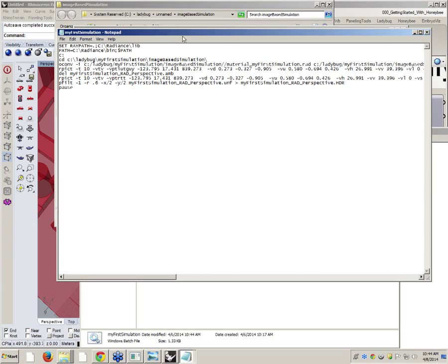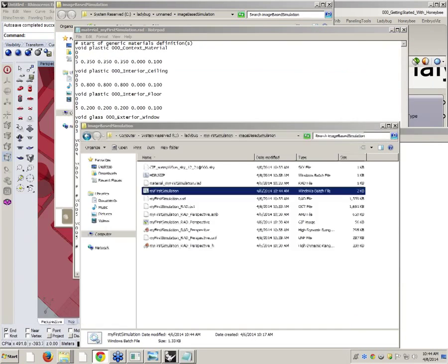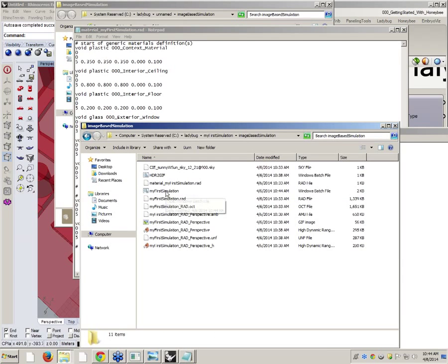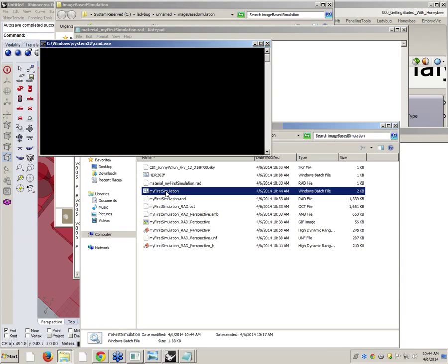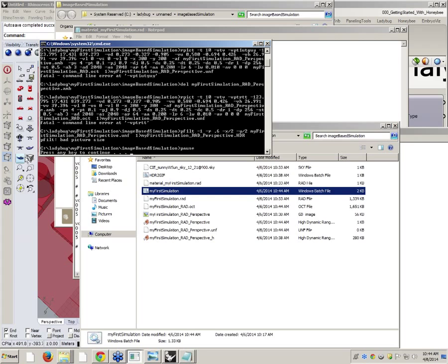This is how you basically debug your simulations, right? So you close this. I changed that exit to pause. Now I run this, something goes wrong, but this thing pauses here, right? So I can go here and say, oh, fatal, command line error at VPT something. You see, command line error is something. So you can basically read and see why it went wrong.